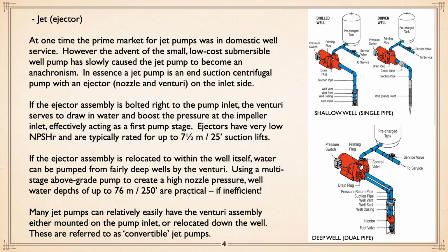Now, it's limited to a lift of about 25-foot maximum, and there's a couple of ways of installing them, either in a well, foot case, all this stuff, or with a well sand point, which is really not so much the pump issue. But basically with that, there's a single pipe.